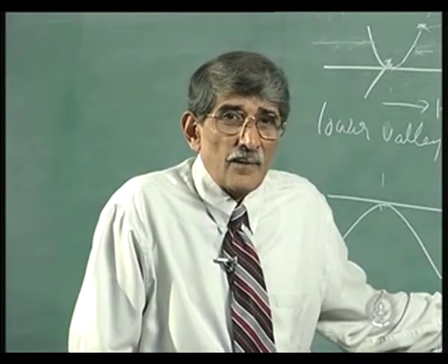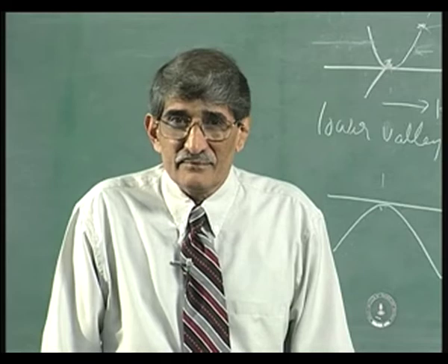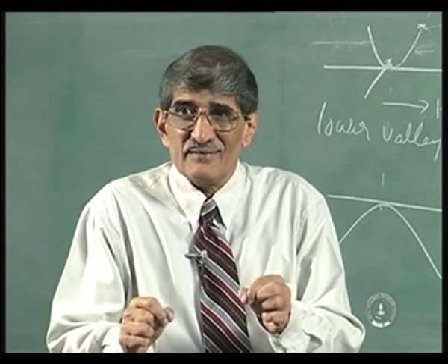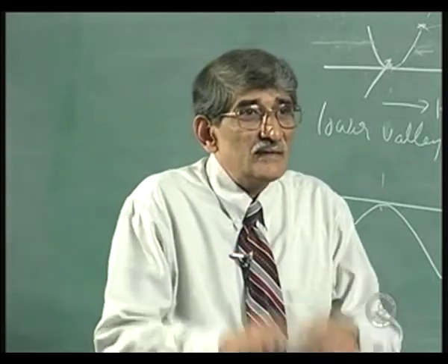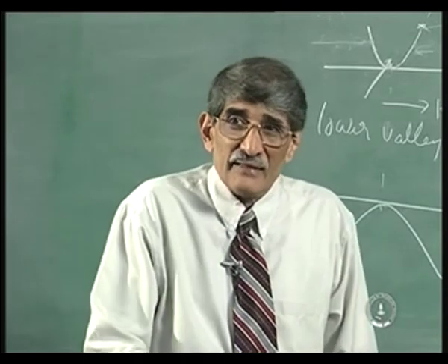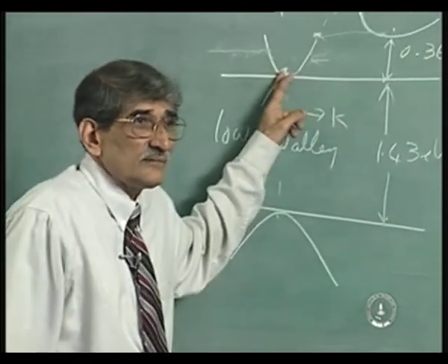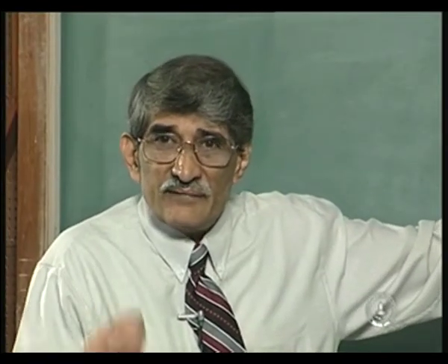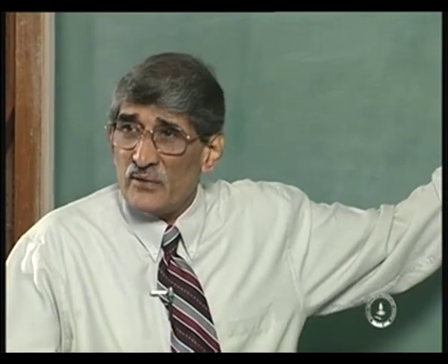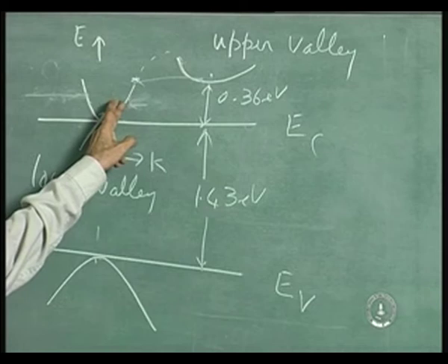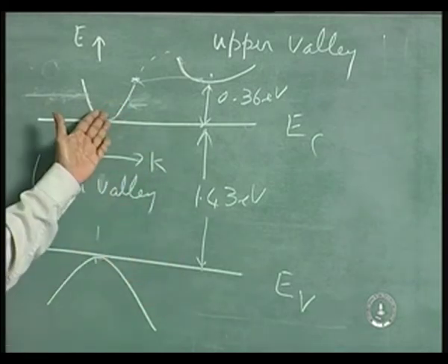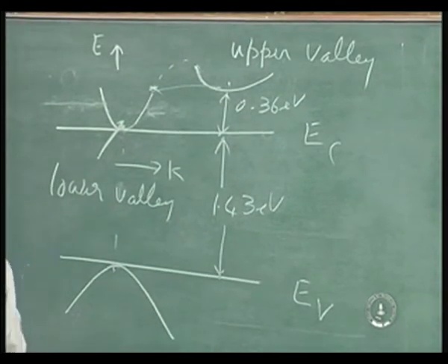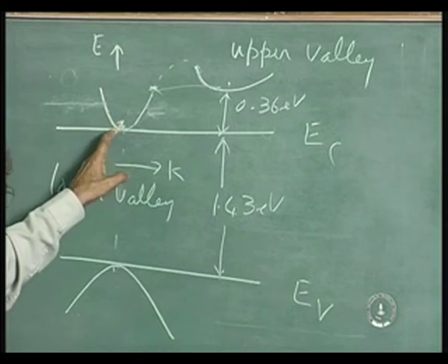In gallium arsenide, an additional field comes up. What is the additional field due to? Between the gallium and arsenic, there is a net charge difference. So, between the two atoms, there are additional forces coming up. Because of that, you have the effective mass smaller. That is the physical concept. In terms of the energy band diagram, this is sharper there. The effective mass itself comes up because of additional forces present between the atoms in the crystal. Here you have extra forces coming up because of the charge difference between the gallium and arsenic atoms. That is why effective mass is much smaller here compared to that of silicon.